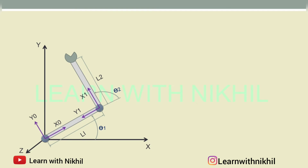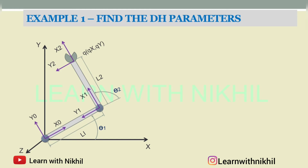So DH parameters are according to the links. So this is the final end effector. Here also we have plotted the coordinate, this is x2 and y2, and this is qx qy. So this is the coordinate qx qy which we have to reach. So we have to reach this point using the angles and the link length. So for this we have to find the DH parameters. DH parameters are the 4 parameters which we had studied earlier. So we have to find the DH parameters for this particular robot.